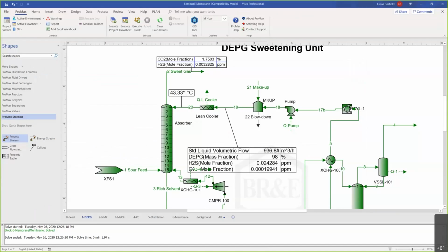You can use it in high concentrations, which means that you have low reboiler duties. It has a low heat of reaction with CO2, which can become important. I have seen cases where you have piperazine present and the heat of reaction gets high, but the heat of reaction is high with DEA as well. So just generally speaking, I would say for CO2 capture, activated MDEA is going to be preferable to DEA.